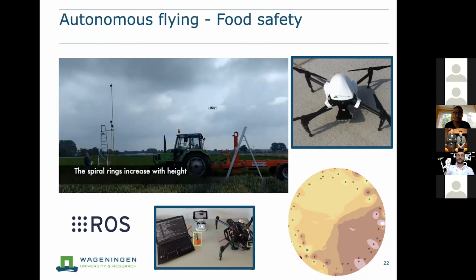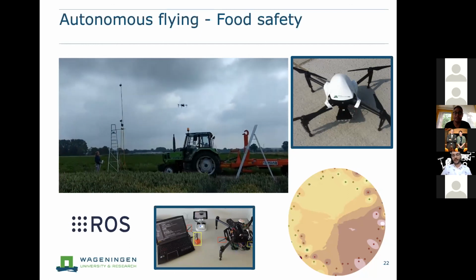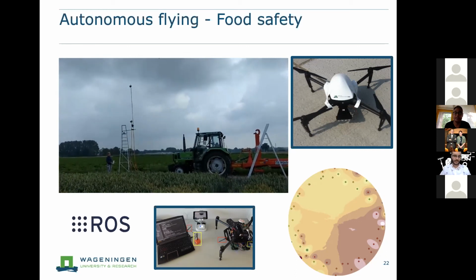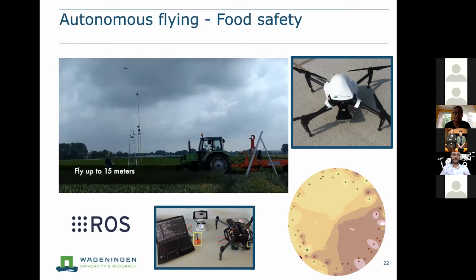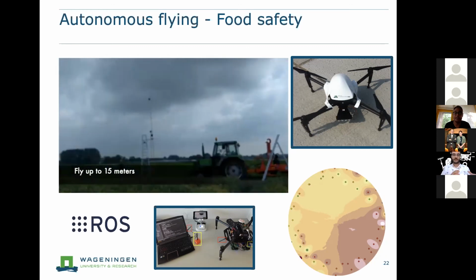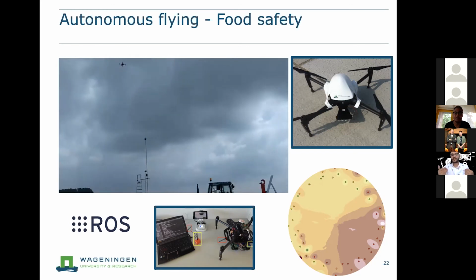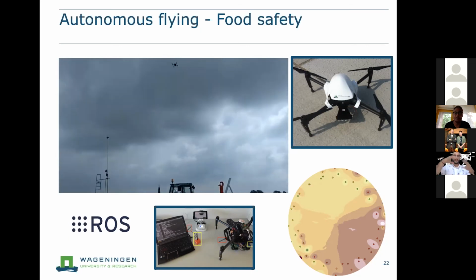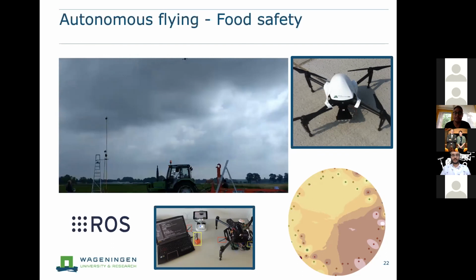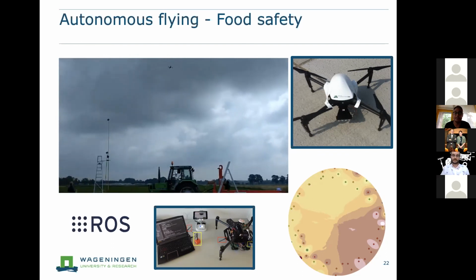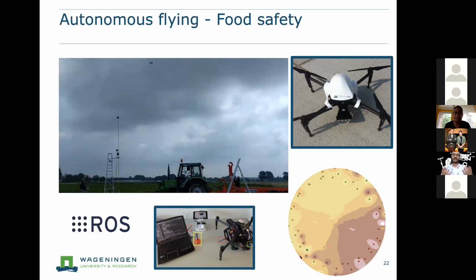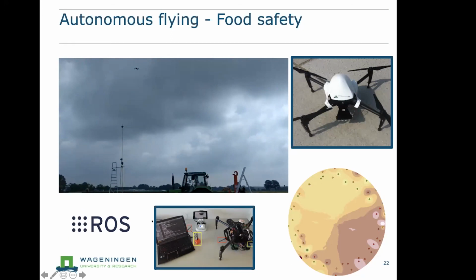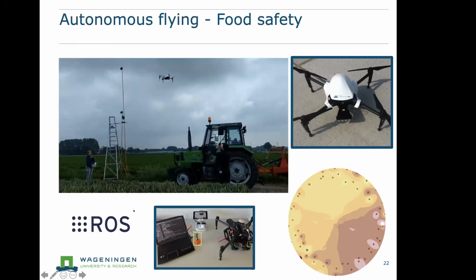We are doing this because, again, before flying and acquiring images, there is still a large process of sensor calibration. Usually calibrating the sensors is the first step, so we make sure that we have reliable data. And it's not just about detection, because those are electrochemical sensors. The output will be a voltage, but then we also need to convert this voltage into parts per million, ppm, which gives an exact value of the amount of chemical that we have in a determinate site. This is also done with ROS.